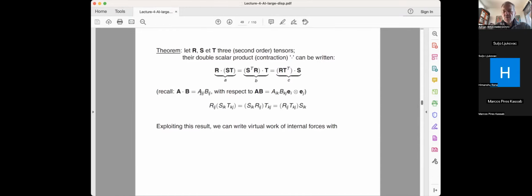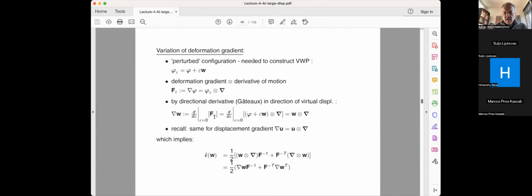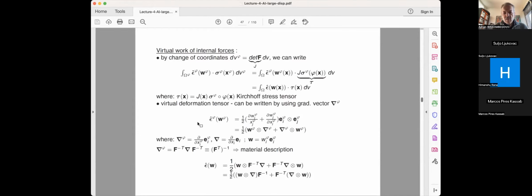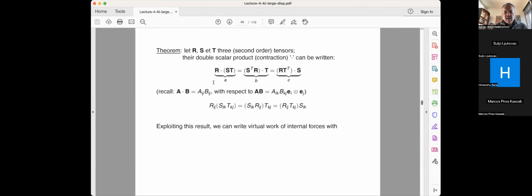So this is really the way you compute your work. You take each and every component of the strain, multiply with the corresponding component of the stress. You have from 1,1 to 3,3, all these 9 components. With symmetry, actually, you have 6. And basically, you get the corresponding work. That's what we mean by the scalar product, which features in this internal force computation sitting here.